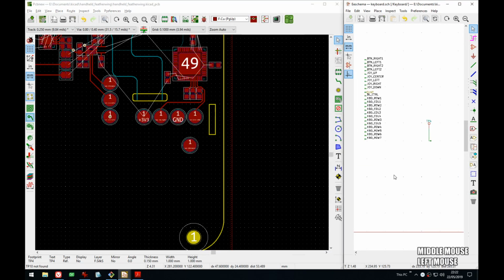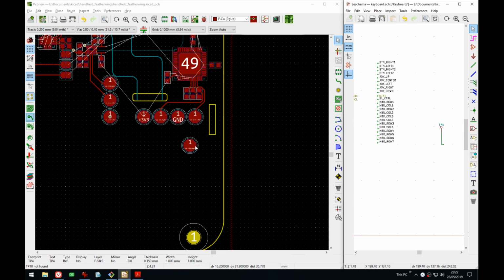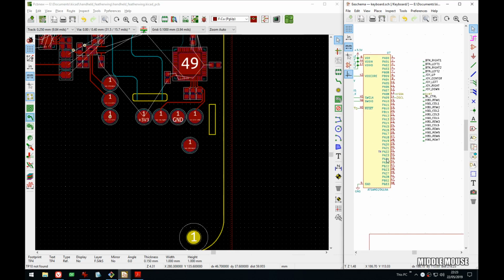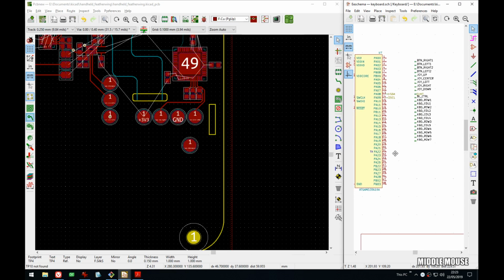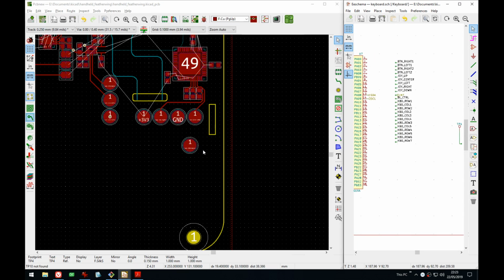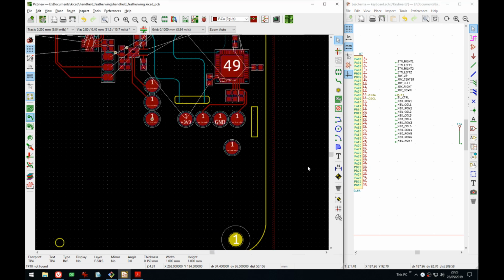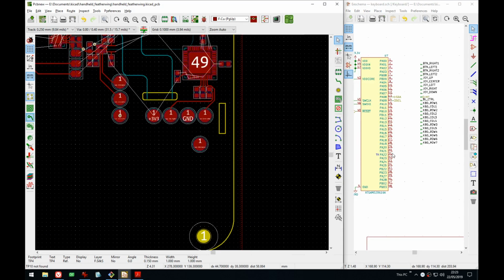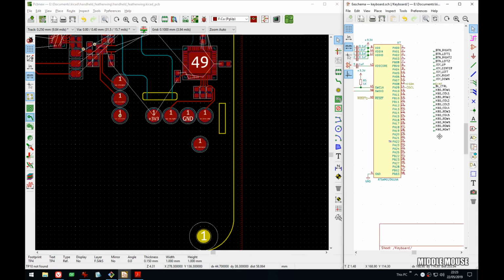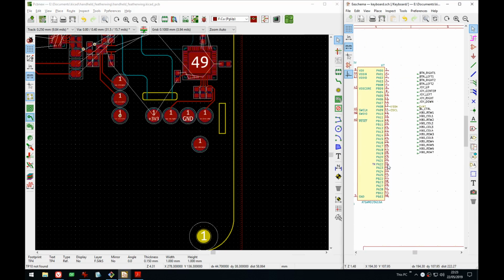So yeah, if you missed the previous stream, this test point is for the UART. If we want to debug this microcontroller, the UART TX is right there. So I connected it to a test point so you can solder and have the UART prints as well. But right now we don't know where that's gonna go.